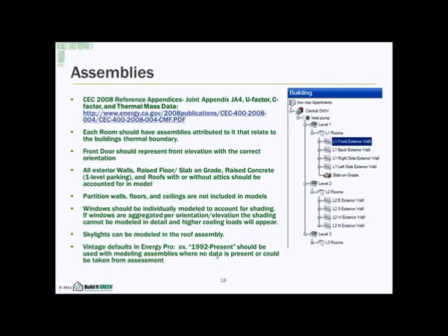So if each of the dwelling units have partitions that pop out and cover the windows to a degree where you can call it a side fin and it's giving shading, you won't be able to capture that if you add up all your windows. But if you have individual windows, you can capture the shading capabilities of each of those windows. And that can also help improve your cooling loads if you're in a heating dominated climate zone.